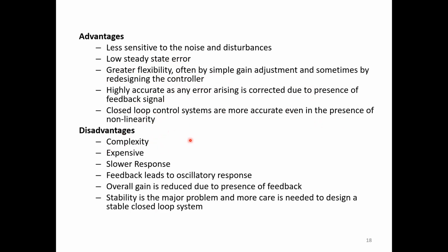And what are the disadvantages? It is complex, expensive, with slower response. Feedback leads to oscillatory response. Overall gain is reduced due to the presence of feedback. Stability is the major problem, and more care is needed to design a stable closed loop system.